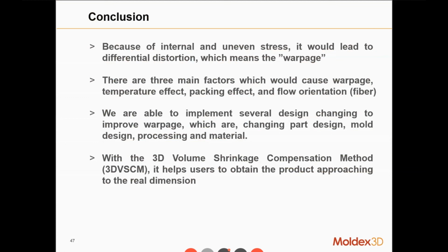Okay, next is today's webinar conclusions. Because of uneven stress, the differential distortion will cause the warpage, and by considering these three main factors: the temperature effect, packing effect, and the fiber orientation, it will help to improve the warpage.